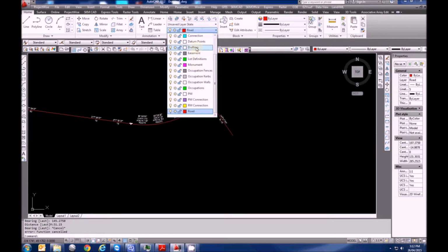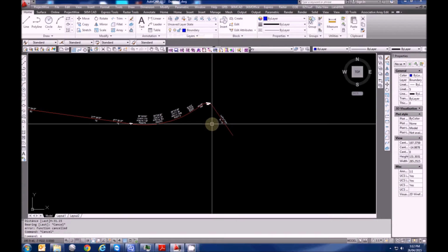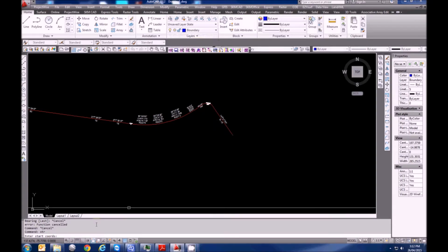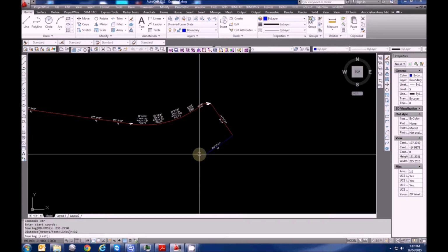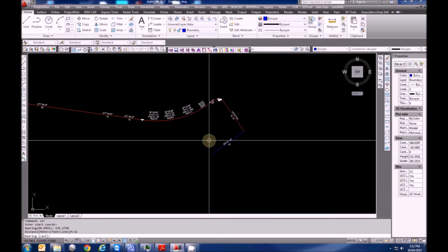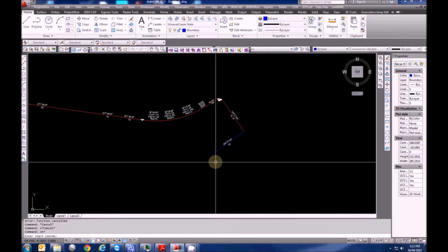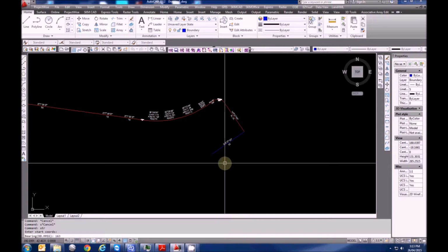So I'm just going to switch my layer to boundary, and we're going to go along the back. I've just done an XTR there, you'll see, it's just a shortcut, saving me going up to get it from the menu button. 335.2750 for 32. I actually got the next line coming from, I don't need the calculator here, 58.142, 37.544 minus. Okay, so we're going to go STR down the line there, 163.3709, 20.608 is the number that I've calculated there.